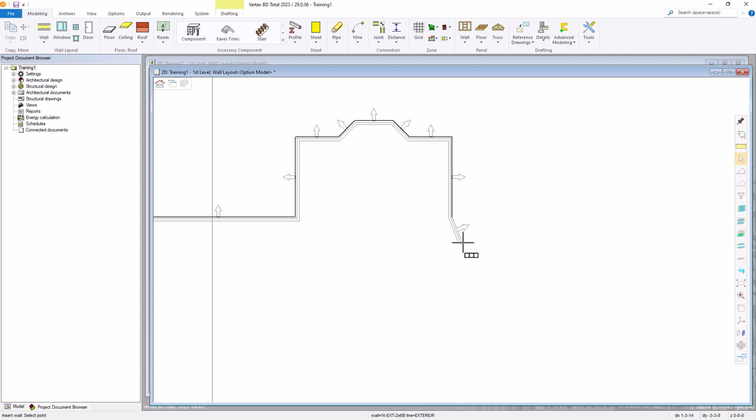Let's say for the next segment, we have a bay and it's angled at something other than 45, let's say 30 degrees off this Y axis. And we know that the Y axis, it's 4 feet from this point. To add that in Vertex, we'll hit 0 to bring up the X axis, but since we do not want any value in the X axis, remove that 0. We'll type -4 feet because we're still moving downward.